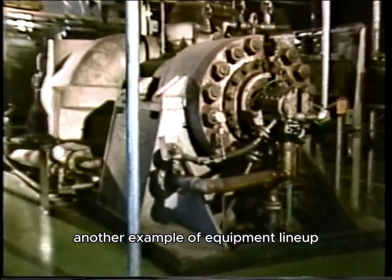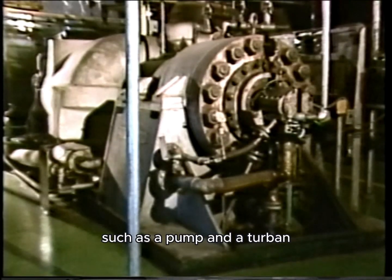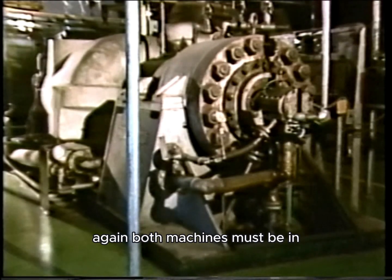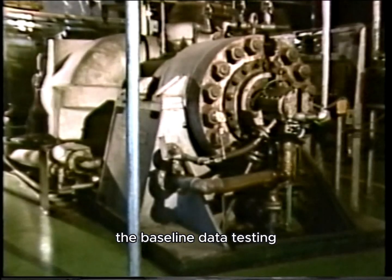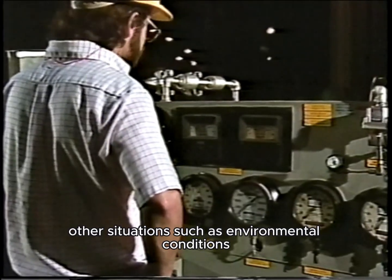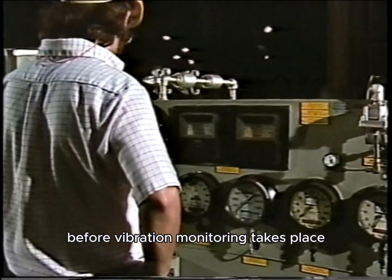Another example of equipment lineup is when two different machines, such as a pump and a turbine, share a common foundation or bed plate. Again, both machines must be in the same condition that they were in during the baseline data testing. Other situations, such as environmental conditions, should also be checked before vibration monitoring takes place.